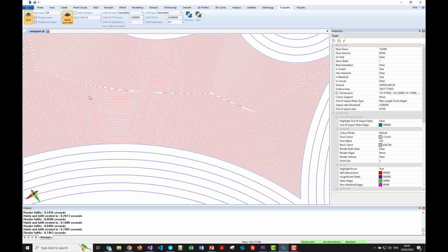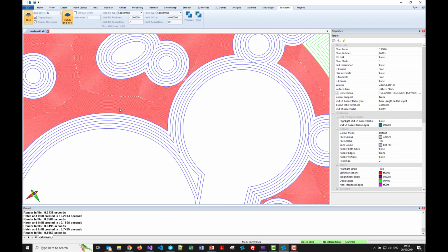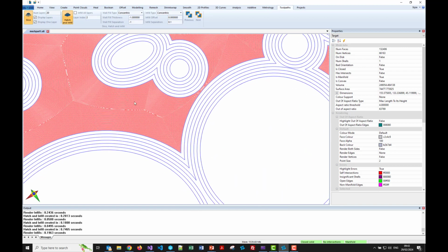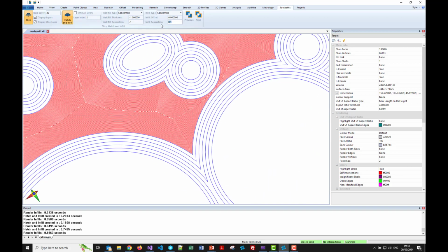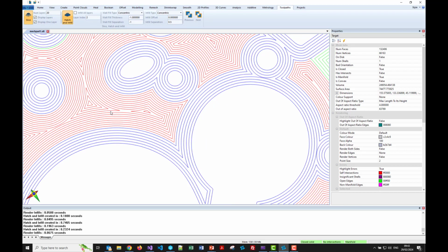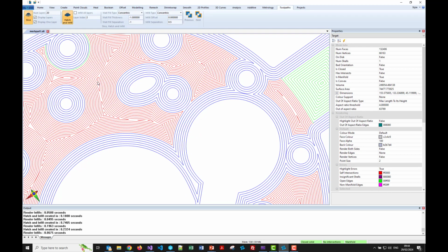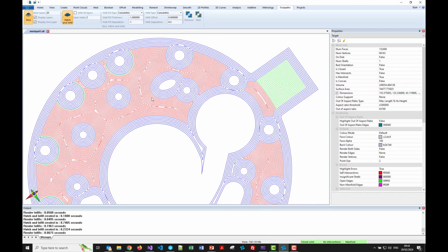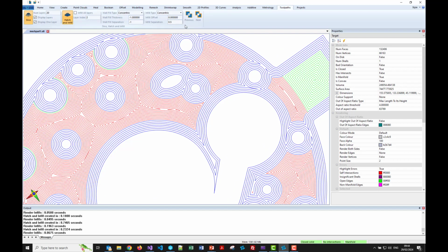And you can see it's very tight, but you still have these kind of seams. So yeah, when you have a very tiny separation like that, you are going to kind of fill everything in. But I suspect that's too tight for a real application. So that's one of the issues with this offset type approach, is that it can sometimes leave gaps that need to be filled in. And that's why I'm just going to put this back to the default.